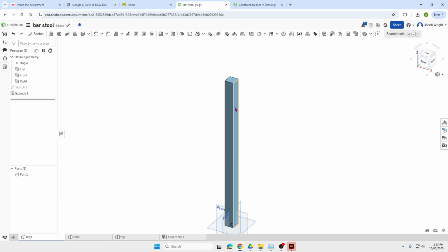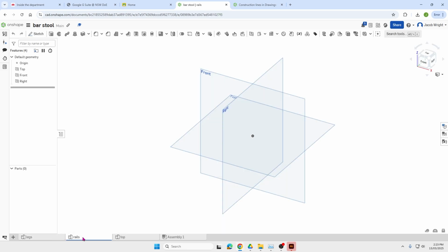So for my bar stool, I'm going to use mortise and tenon joinery. So really common joinery for a frame like this. An alternate option would be to do dominoes. If you're doing domino joinery for this, you could draw all the dominoes in very similar to this mortise and tenon, and I'll show you how to do that in this video as well. So I'm going to start off with my rails before I come back and draw the mortise and tenon joinery, because I'm going to need a bit of detail about the size of my rails before I start drawing in where the tenons are going to go. So let's go across to my rails for now.